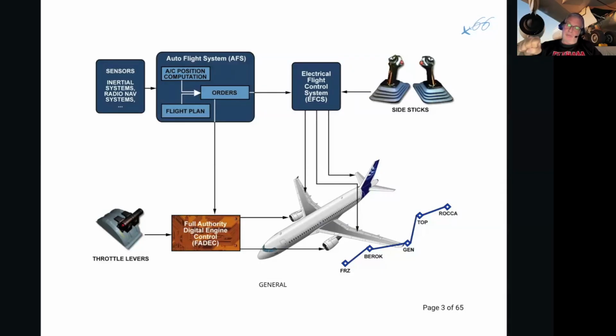As the pilot puts them into the climb detent, the auto thrust is active, and it remains active for the remainder of the flight. Just before landing, the pilot is asked to retard the throttles, and he hears the command "retard", which means take them out of the climb detent and put them in the idle detent, and that's when the auto thrust disconnects on an Airbus.